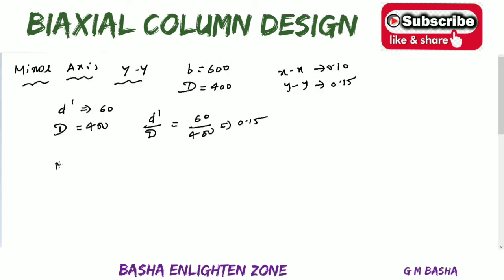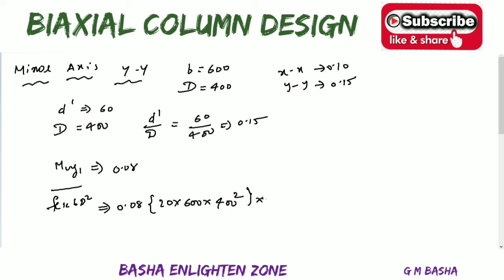Okay, then solve this one. Muy1 by fck bd square will be equal to 0.08. So solve this one: 0.08 into 20 into, here b changes from 400 to 600 and d changes from 600 to 400, into 10 to the power of minus 6 as usual, and simplify, you will get 153 kilonewton meter.